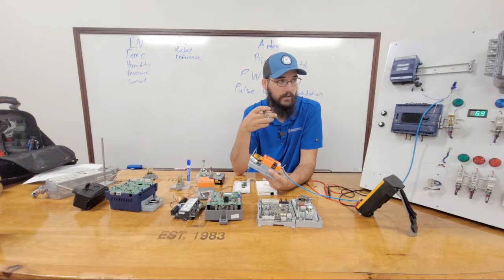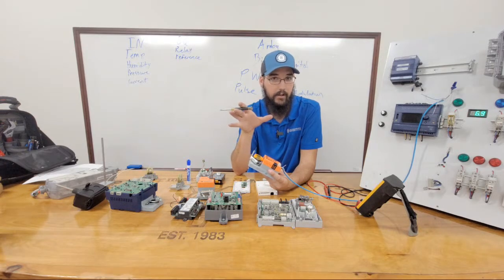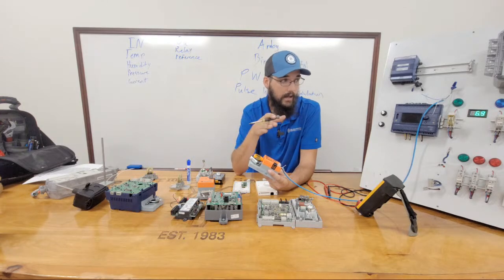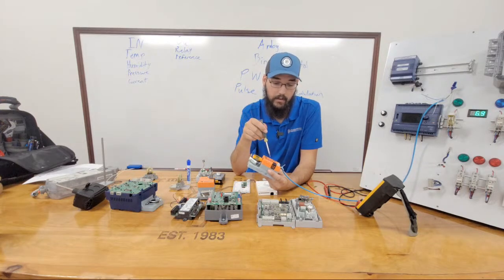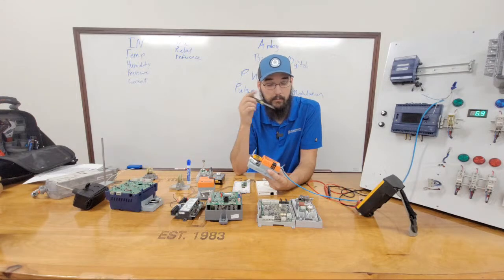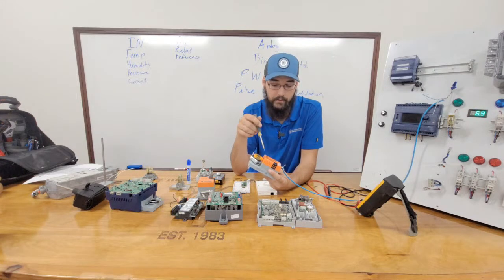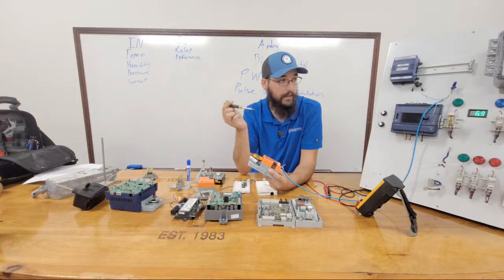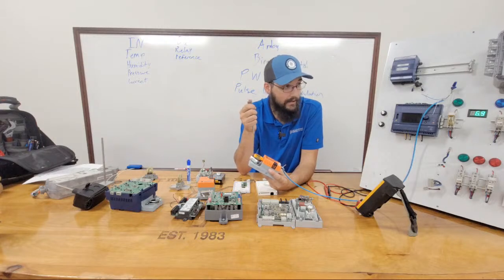And it will cause the entire control sequence to get very erratic and out of control to where it just bounces up and down, and it never actually locks in where it needs to. And that would be because, genuinely, you walk into a controls shop and you need to replace this actuator because it won't spin, and this one's rated for 95 and he gives you one rated for 180.